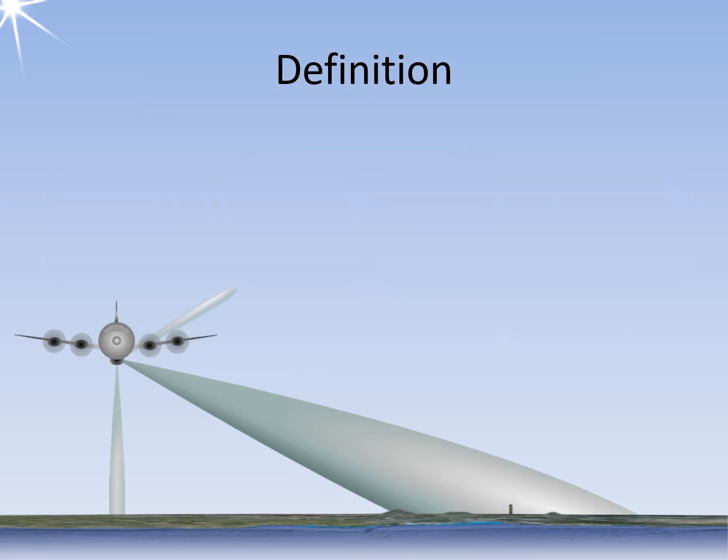A side-looking radar is a high-resolution imaging radar that uses a real aperture. This active sensor has antennas positioned in a plane that is perpendicular to the aircraft's axis and flight path. Like any radar system, it can transmit and receive signals regardless of daylight and weather conditions, allowing it to generate high-resolution strip maps of the ground. It is particularly effective for mapping larger areas of terrain with photo-like detail.